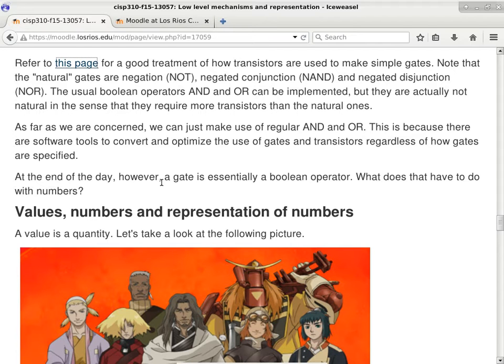But underneath is a very uniform type of design. So they will all be like NAND 2 gates, they will all be NOR 2 gates, and whatnot. So with those, you will have to eventually translate everything down to NAND 2, NOR 2, or whatever is native to that design.